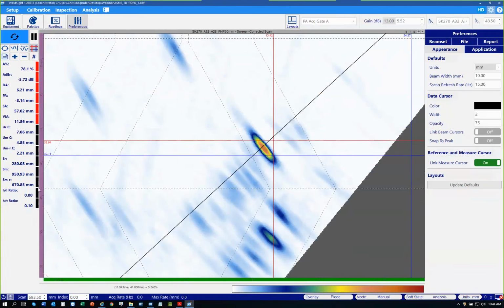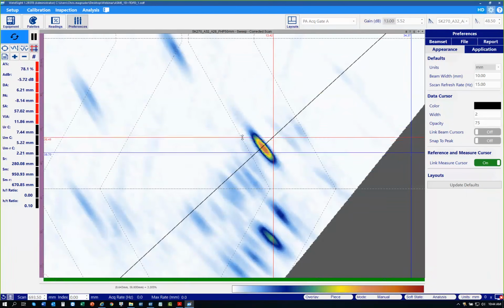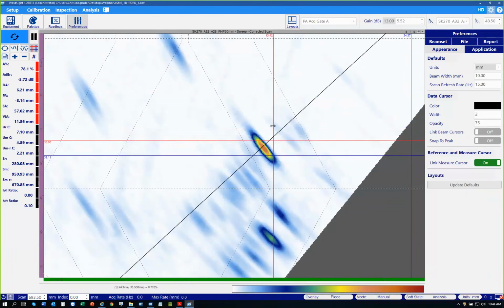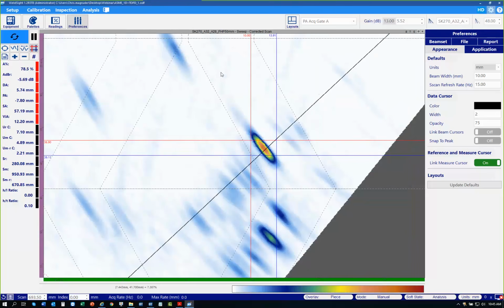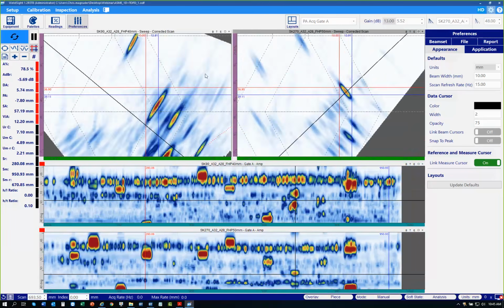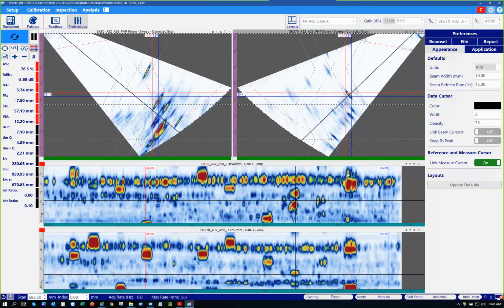So I've got a through wall height dimension of about the size of a weld pass, a little less, 2.2 here. At 6 dB, it would be a little bit larger drop. I'll identify the area on the index axis as well here. So this is a pure amplitude sizing that only works on favorable orientation, typical of sidewall lack of fusion. I'm going to do my linked sizing directly on the C-scan.